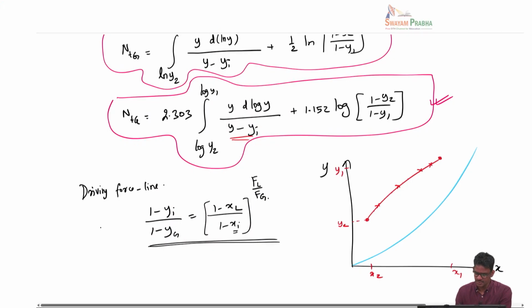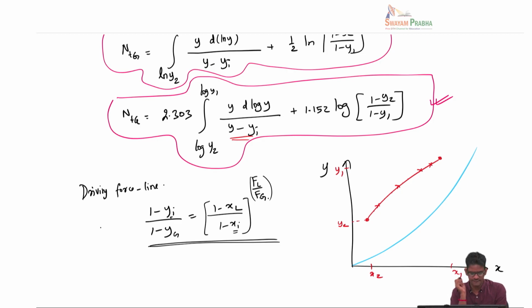If I use K type mass transfer coefficient, this will be a straight line with a slope of minus Kx by Ky. We have seen that before. But if I do this with local mass transfer coefficients, F type coefficients for concentrated mixture, this need not be a straight line, it will be a curve. It gives you a relationship between x and yi depending upon the ratios of the mass transfer coefficients. So we have to know these two mass transfer coefficients FL and FG, and then yG and xL are the points along the operating line.